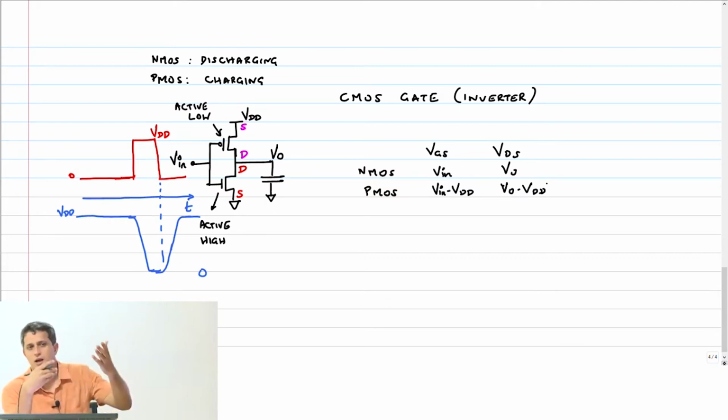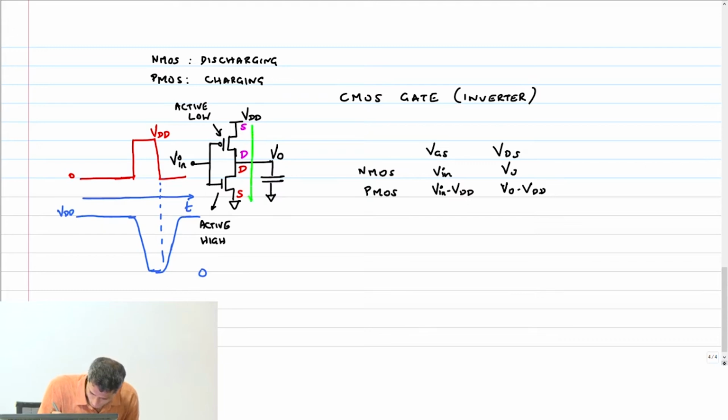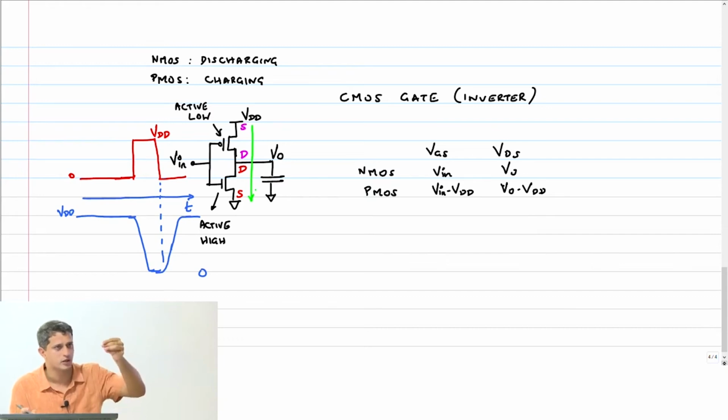Now there is some VGS and VDS on the NMOS, and some VGS and VDS on the PMOS. What should happen to these two currents at all times? They both have to be equal in magnitude. Remember that the current will always flow from supply to ground like this, assuming that one transistor is allowing conduction. For example, if the NMOS is off and can allow no current, then there can be no current in the PMOS as well, right? It's in series.